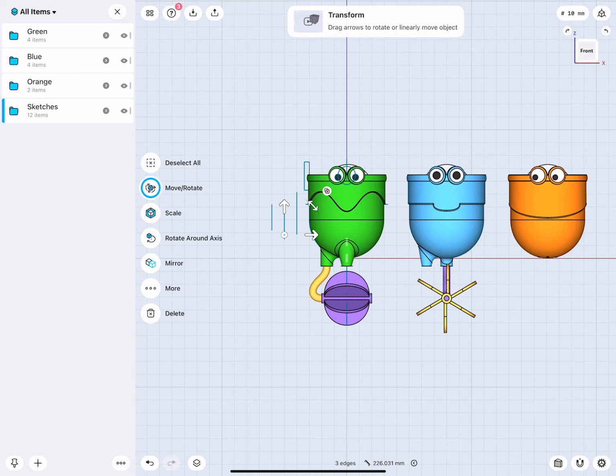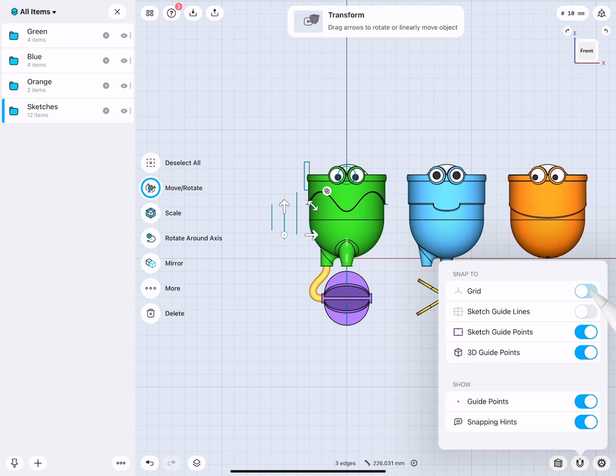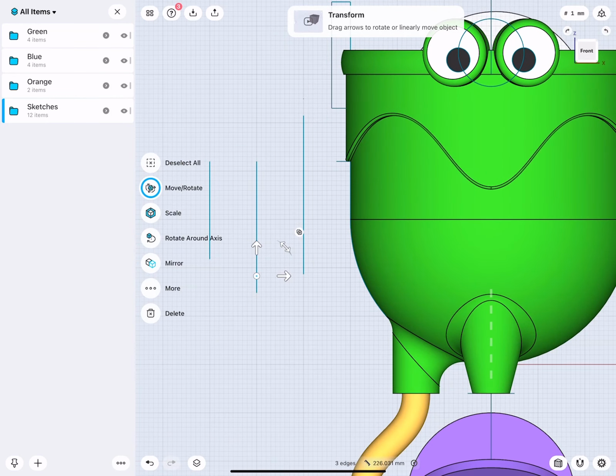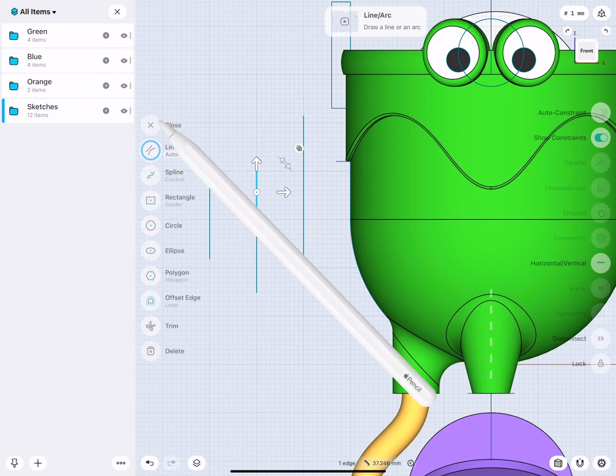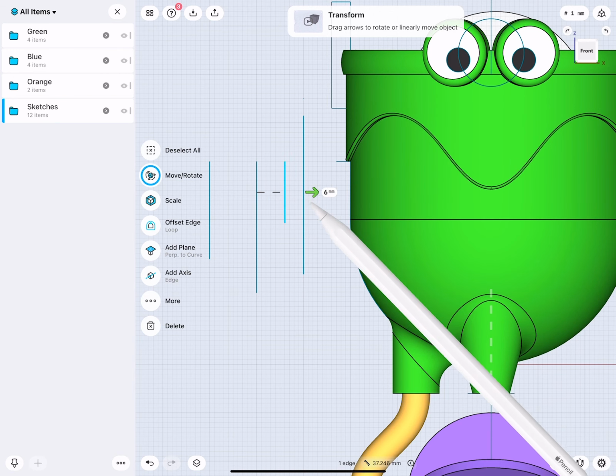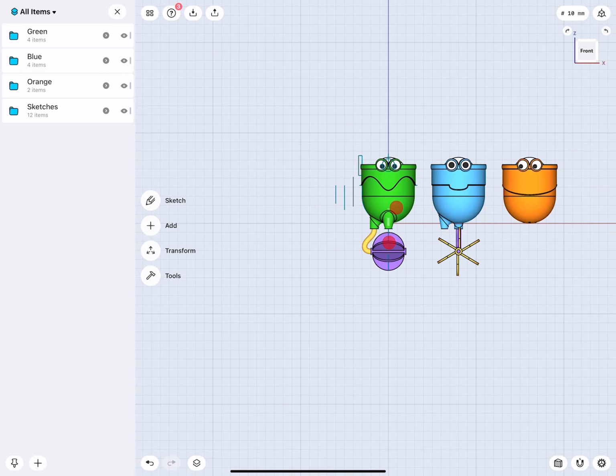Because I'm moving sketches from the XYZ plane away and back, it's also really important you have your grid snapping turned on. Because then, how could we say this, peace of mind. We can see where this is, and when we select this and go to move, it's so easy to simply move it back into the center area.